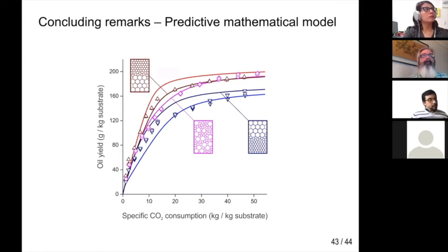We divide our conclusions into two parts. This first part refers to the findings of the mathematical model used in the various simulations. A distortion dissolution diffusion model with a linear driving force was developed to predictively simulate supercritical CO2 extraction of pelletized oilseeds using the equilibrium partition sorption isotherm isobar of Urrego and coworkers and the oil solubility correlated by Del Valle and coworkers.